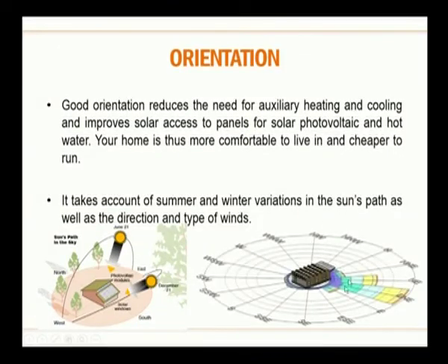And this is an example of a wind rose pattern. As you see for this building, it is an example, and this side has more prevailing winds. Even though there is wind from all directions, the most frequent wind direction is towards the east and northeast actually. So, the windows are oriented according to this direction to invite the cool breeze inside.